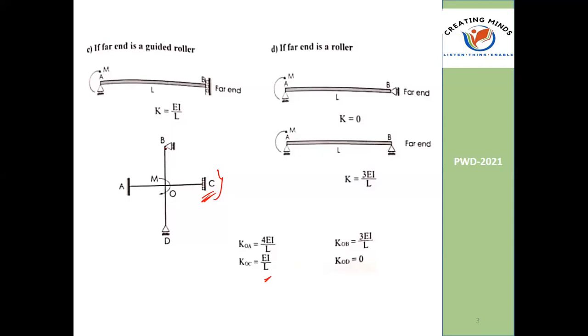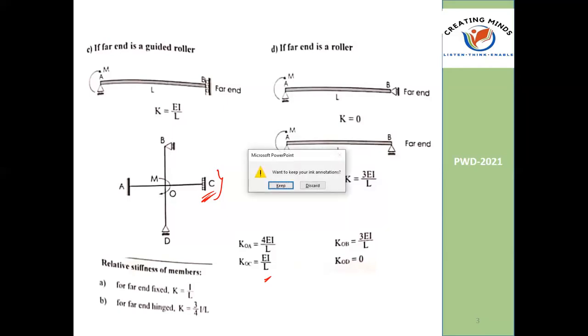Generally we will not give an axis support as a hinge, because a hinge will provide 2 vertical reactions and it will allow moment. If I provide it in the axial way, moment will be allowed, and practically it's not possible to give such kind of structures. So generally they will provide a roller. The thing is very clear. Please keep the concept.